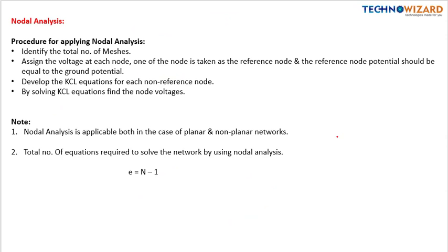Okay, so next is nodal analysis. What is nodal analysis? Let's see. The procedure for applying nodal analysis is: identify the total number of nodes, assign the voltage at each node.